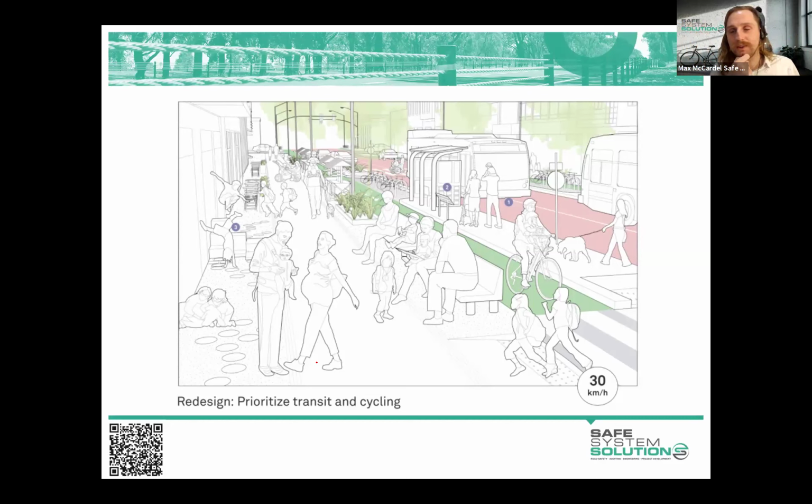They're more likely within an audit to recommend things like consider doing swept path diagrams to confirm specific turning movements can be met, or additional traffic modeling to confirm the phasing and the times are all set up if it's a signalized intersection. But generally, I haven't seen either of those two reference each other and recommend one or the other.